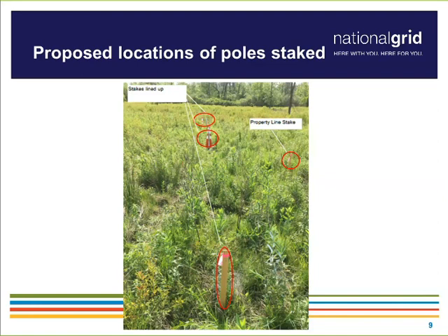In this case, you can't see that. There's a lot of vegetation. So we asked that everything be staked out in the field, and you can see that all the stakes here lined up. I've got them circled in case you can't see them. And we also see the stake for the property line. So we can make some visual inspections and see how all this is going to lay out.